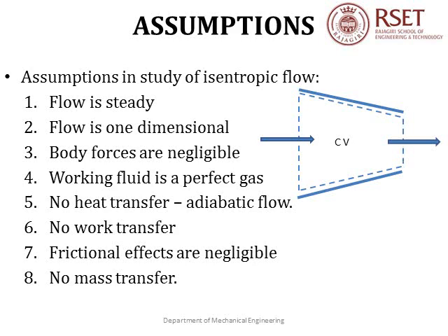Frictional effects are negligible. Note that it is negligible, not absent. That is, it is a flow through a duct, so there will be skin friction. But as I mentioned earlier, the length of the duct will be comparatively smaller, and because of that, the net viscous effect developed within the duct can be neglected with respect to the changes brought in by the change in area. The variation that the frictional effect has on the fluid properties is negligible.